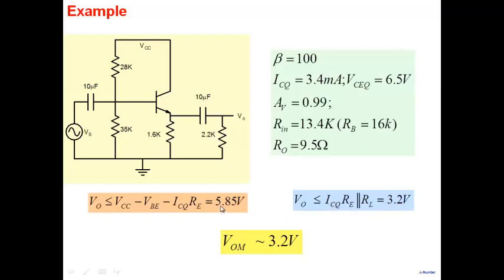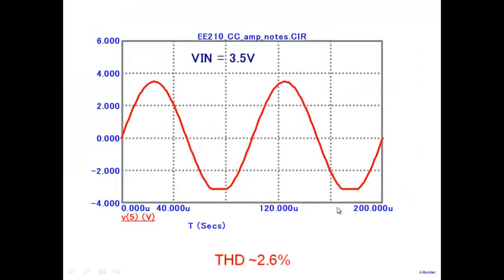It's not coming from saturation. It's not coming from my voltage not being able to exceed VCC. All of that is not the issue. The issue is the current here. And that's why I get a clipping here. And the moment clipping occurs, note that harmonic distortion starts increasing, 2.6. Yeah. So due to current limitation here, so let's stop here and